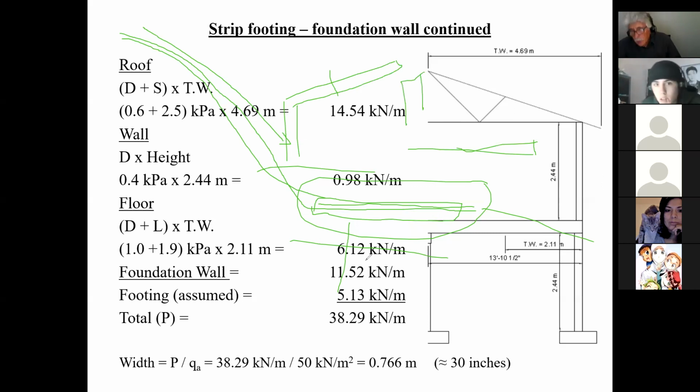And then of course we did a load test to confirm my calculations. And when the hoist was in a certain direction, right? The guy only had 5-pound weights that he could add to the hoist. And I had calculated that when it was in this position, the whole thing would tip over at 37 pounds. So when we were doing the test, the guy put down his 35 pounds and I said, be careful, it's going to tip now. He went to put the other 5-pound weight, guess what happened? It tipped. So was I proud?